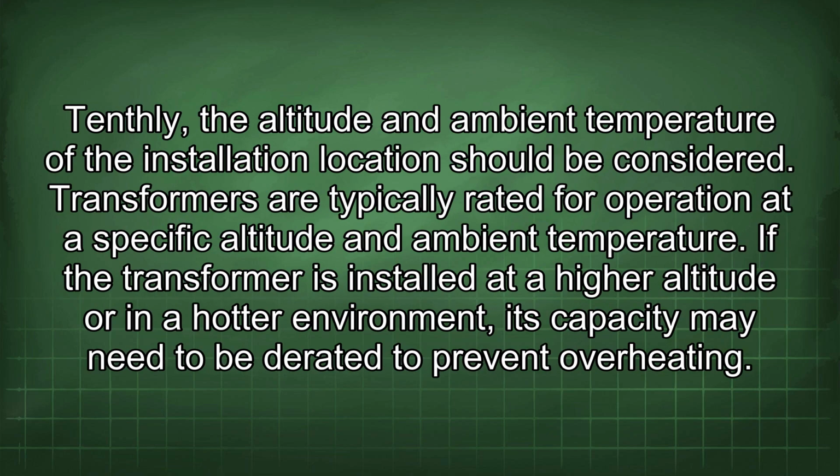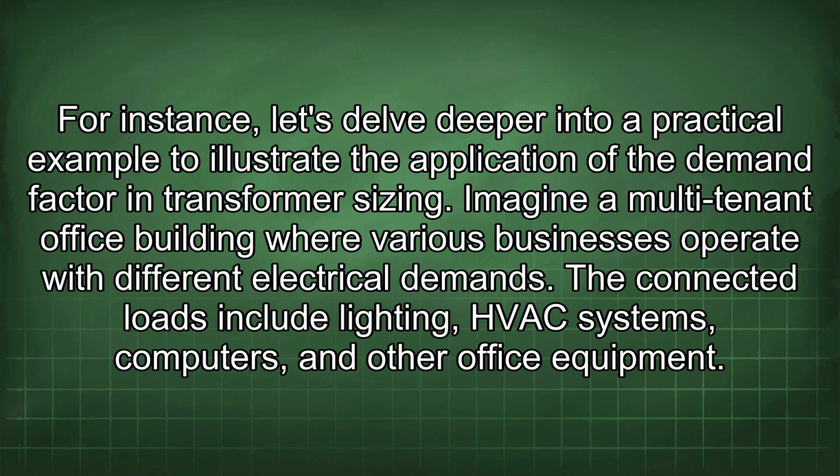Tenthly, the altitude and ambient temperature of the installation location should be considered. Transformers are typically rated for operation at a specific altitude and ambient temperature. If the transformer is installed at a higher altitude or in a hotter environment, its capacity may need to be derated to prevent overheating.